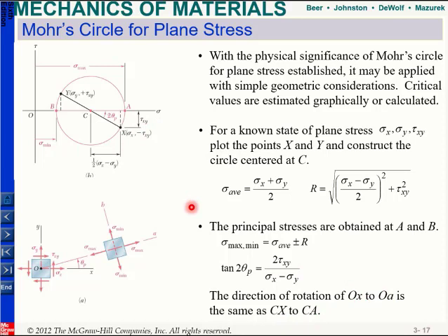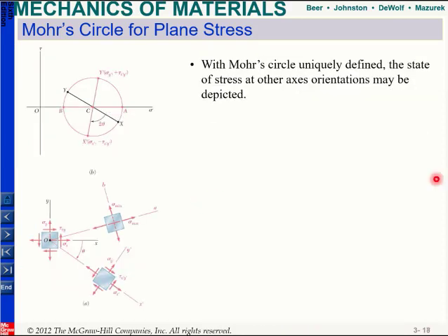All right. And with Mohr circle, we can also find our stresses at any other angle. For example, let's say again we construct our Mohr circle. This is our normal stress and this is our shear stress. In this configuration, you find your point X and your point Y, so we are looking at this XY system. If you rotate it by theta and want to find your new stresses, all you need to do is rotate this by 2 theta, and now this will become your X prime and this will become your Y prime. Then you can use geometry to find these points.